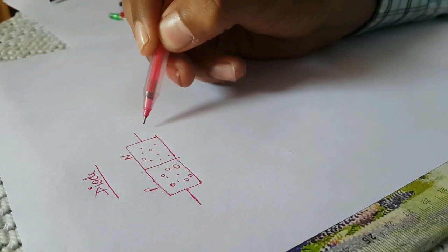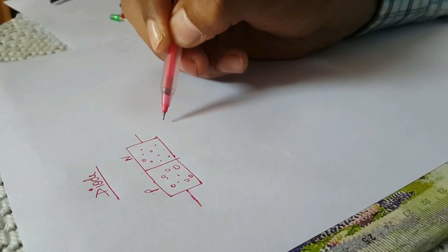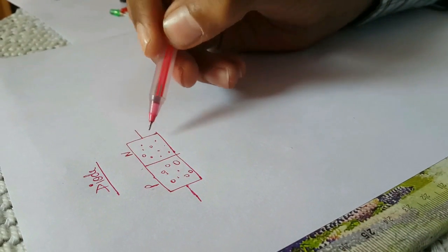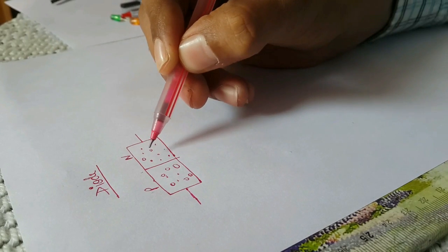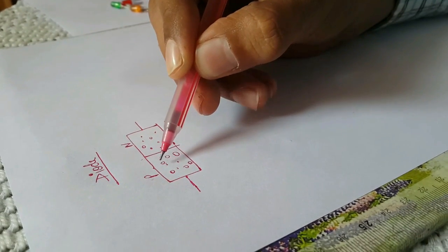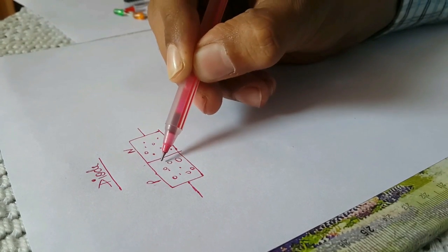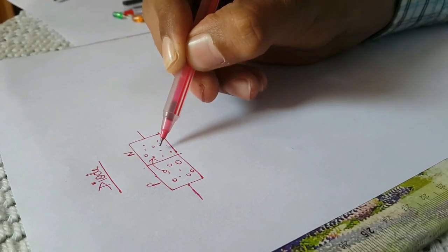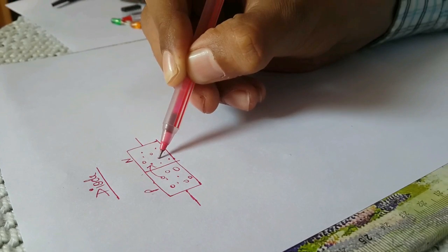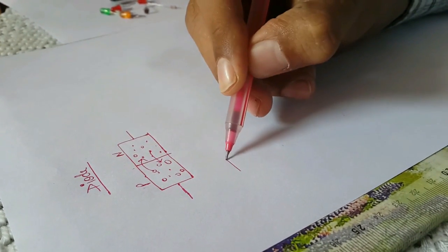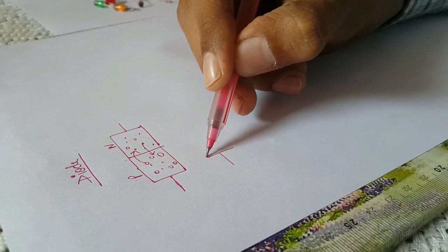When no electric field is applied, that is, no potential is applied across the diode, then due to a concentration gradient, here the concentration of holes is higher, so they would tend to move to the lower concentration, and the electrons would tend to go to the P part in that way, and hence we get a depletion region.